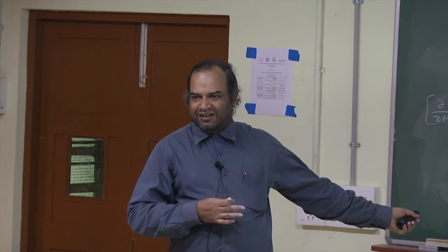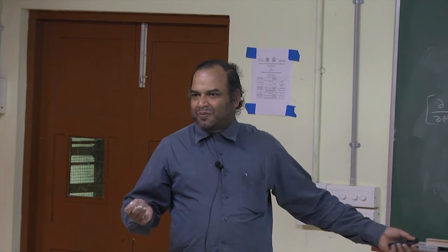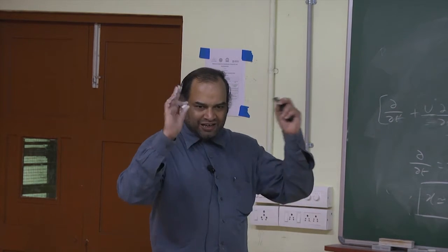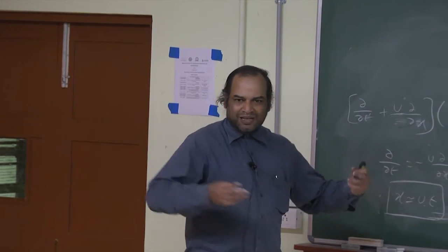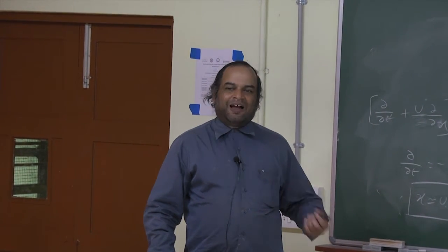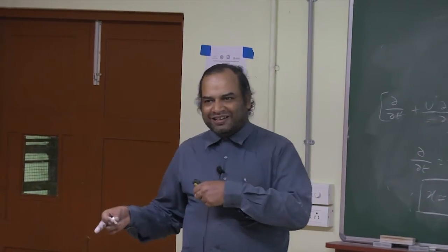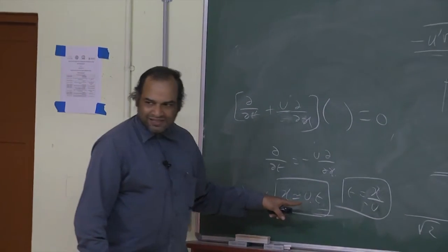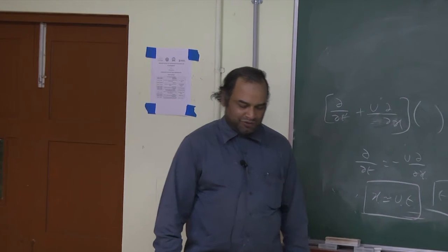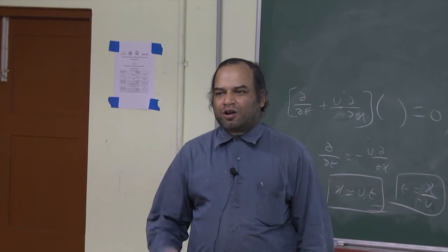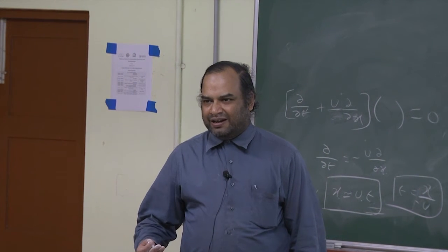On the other hand, if you have a PIV shot, let's say instantaneously, you don't need to do all that. You directly get your k, if your picture is broad enough and detailed enough. One instantaneous PIV picture gives me my space series, velocity at different points in one shot. In fact, if you are using a PIV and want the temporal data, you have to do an inverse kind of Taylor's hypothesis, to come back from space to time. Now, Taylor's hypothesis obviously is only a hypothesis, but remarkably it works in a variety of situations. People have verified that.